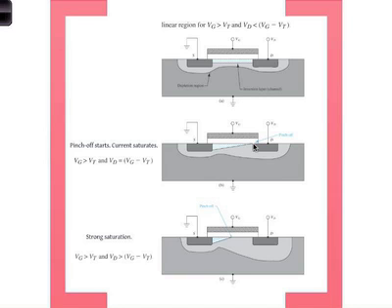It's barely at the threshold. That's what that means. Okay? Because right here, the voltage you have to consider is the difference between VD and the local voltage right at that point, which of course will be determined by the applied voltage VD. Okay, it's exactly the same as we had in the FET.